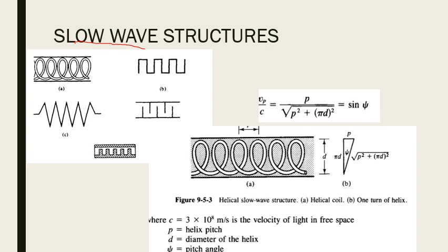So the electron beam will move at a maximum velocity of how much? DC electron velocity. If you recollect the formula, it was always small v naught. Do you remember this, everybody? Small v naught used to be 0.593 into 10 to the power 6 into square root of V naught. Meaning it depends on the square root of how much cathode voltage you can give. We have a limitation because the maximum voltage we give is from the power supply. Only that much we can give.